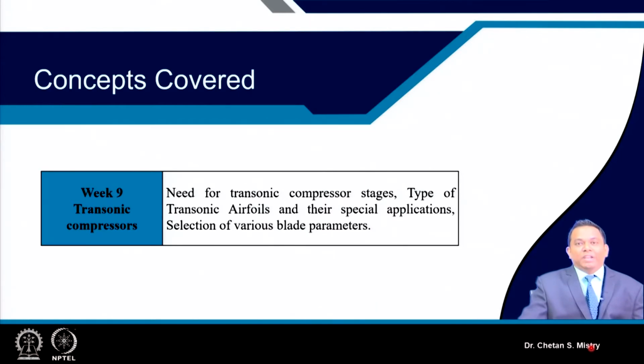But it works worst under off design conditions. Off design may be a change of speed or mass flow rate, and it is possible that the flow will go subsonic. Under those circumstances it does not work fine, and that is why we give some rounding at the leading edge, and when required at the trailing edge.